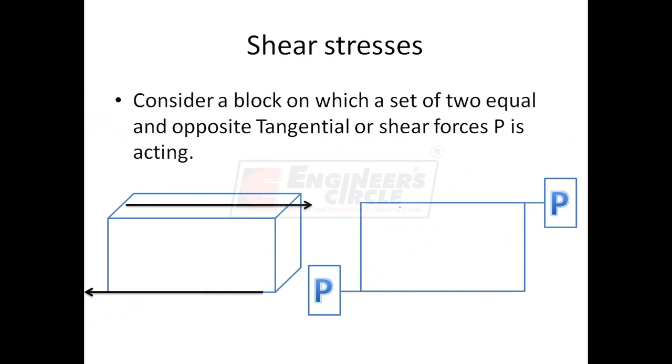Now, shear stresses. To understand shear stresses, we need to know what is a shear force. A shear force is a force that acts parallel to a surface. That is, it is a tangential force. For example, this force is acting parallel to this surface. Therefore, with respect to this surface, the force P is a shear force.